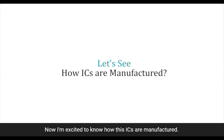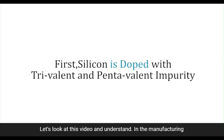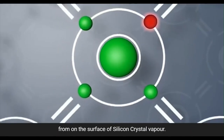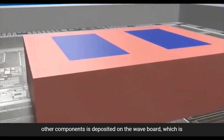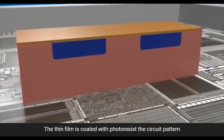Now, I'm excited to know how these ICs are manufactured. Let's look at this video and understand. In the manufacturing process of ICs, electronic circuits with components such as transistors are formed on the surface of a silicon crystal wafer. A thin film layer that will form the wiring, transistors and other components is deposited on the wafer, which is called deposition. The thin film is coated with photoresist.